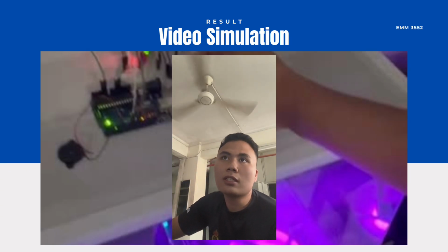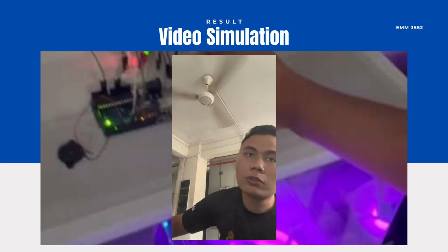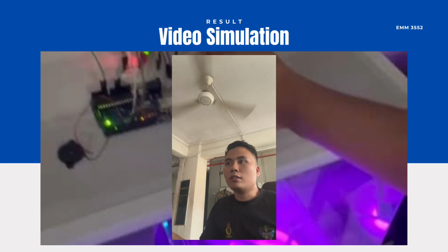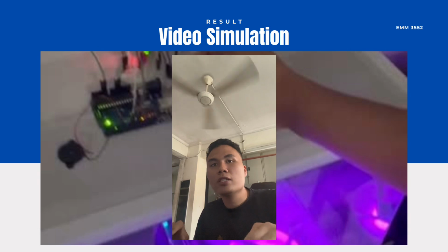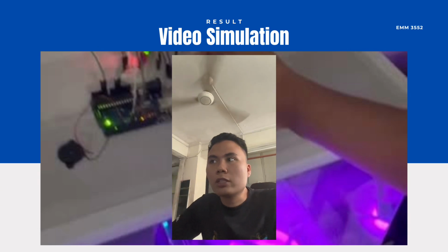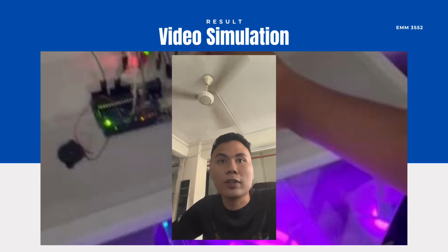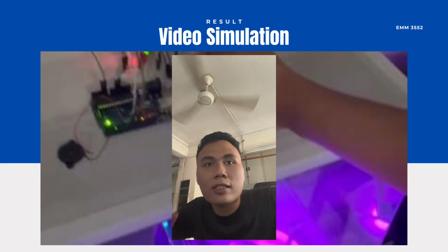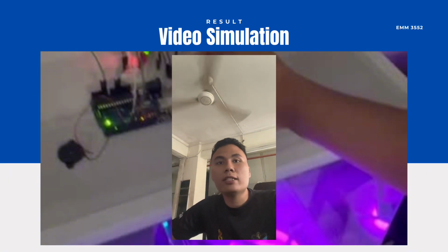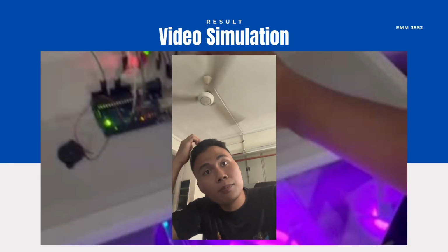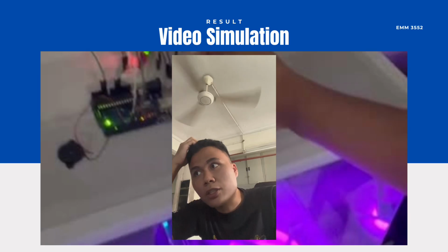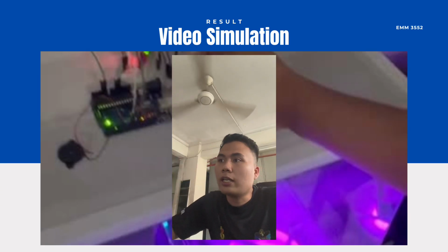So the third device, which is the microcontroller, the Arduino, will continuously read the input from the sensors, which is from the temperature sensor and the gas sensor. It will compare the reading to the preset threshold values. So if the reading exceeds the threshold, the LED will come on with visual light as the visual indicator, and the buzzer will make a noise for the audible alert.